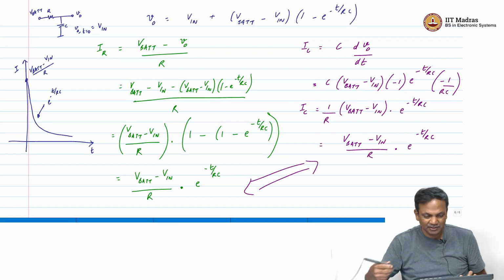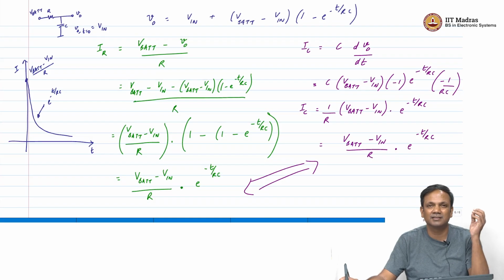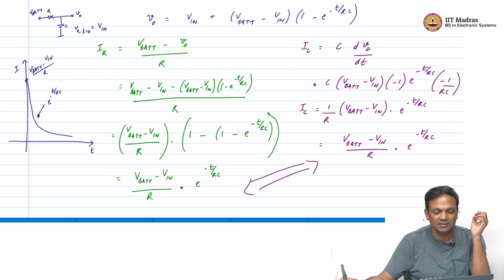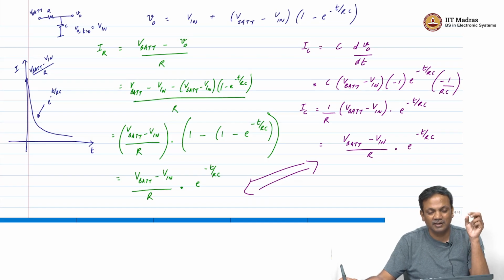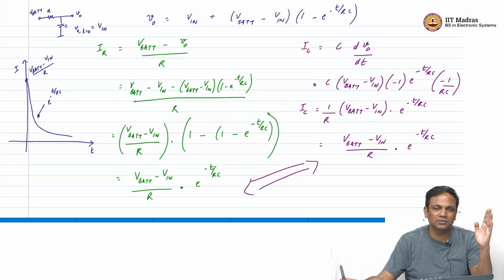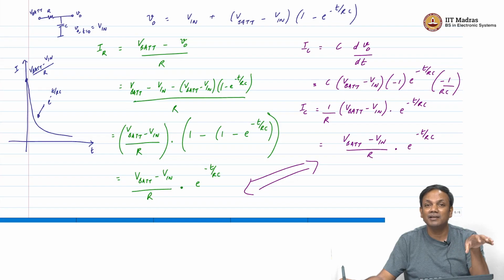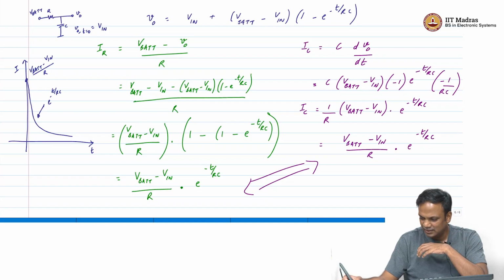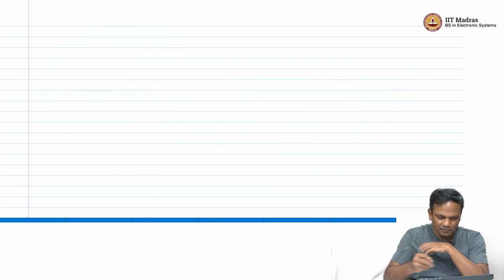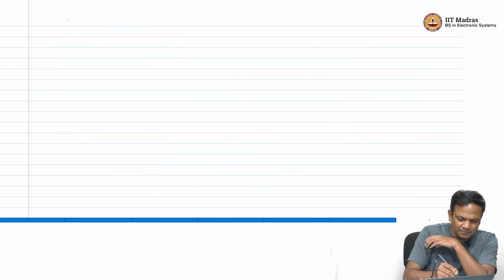So, first thing we should maybe recognize, and this might have been taught to you in one of the earlier modules, and I think it was covered in the video as well, is that you can think of a voltage source as an infinite capacitor, right. A voltage source is indistinguishable in its characteristic from an infinite capacitor. You can think of a battery as a slightly non-ideal voltage source. So, maybe it is a very large capacitor, right. So, let us get to that.